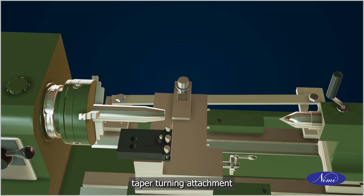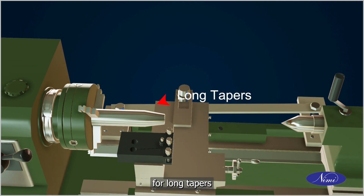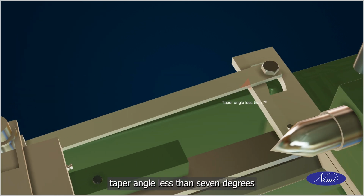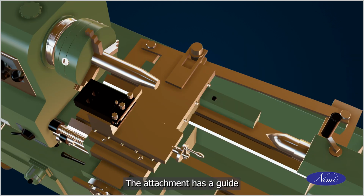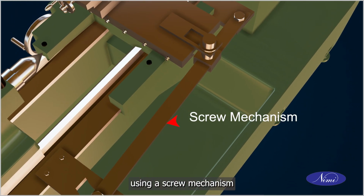Taper turning attachment for creation of tapers is used for long tapers, power feed, internal tapers, and taper angle less than 7 degrees. The attachment has a guide which is fixed along the bed and can be moved to the required taper angle using a screw mechanism.